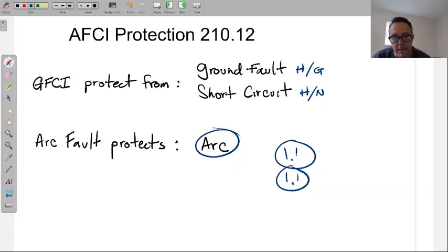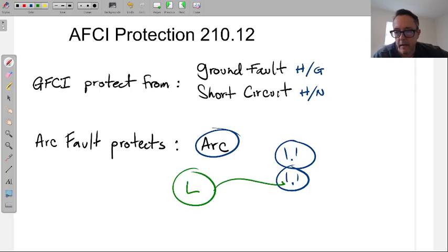What this arc fault receptacle is doing is protecting against an arcing that happens when people unplug devices or loads. And here's the thing that has to actually be going on, which is this load in the on position. You got the lamp on, you got your computer on, you got whatever it is on, and they just unplug it. What is arcing? Arcing is the sparks caused by current.